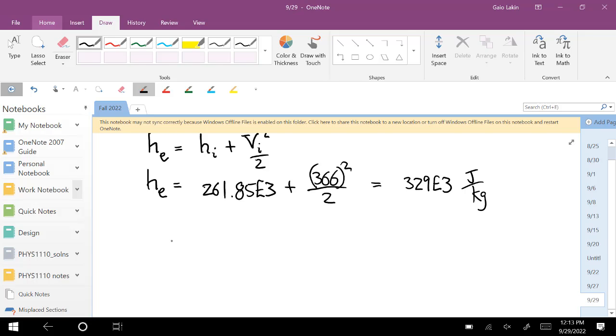So a table of 2 megapascals is going to give you answers that are pretty close to 2.07. So I just used the 2 megapascal, a 134A table at 2 megapascals.